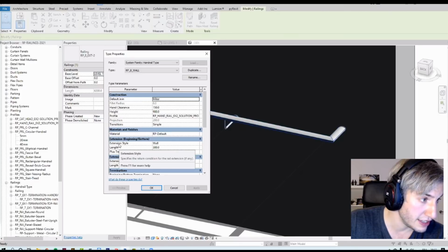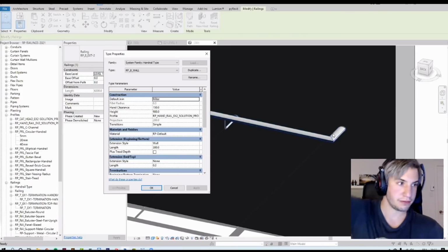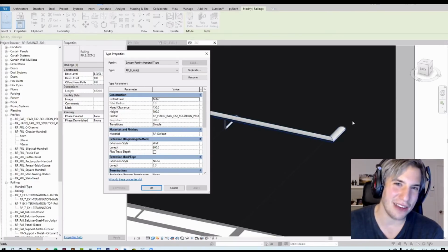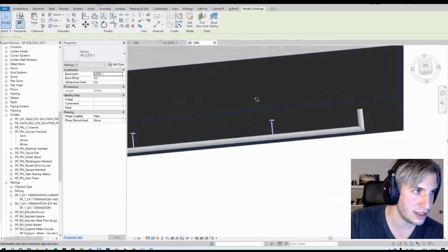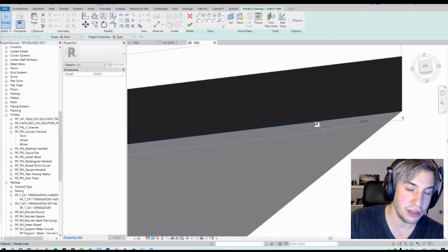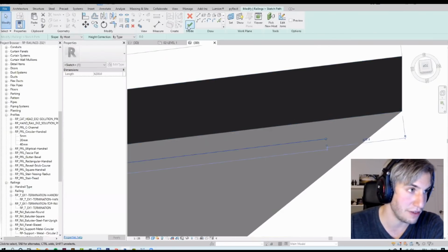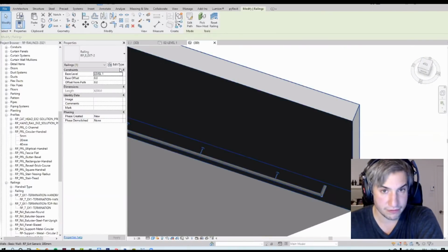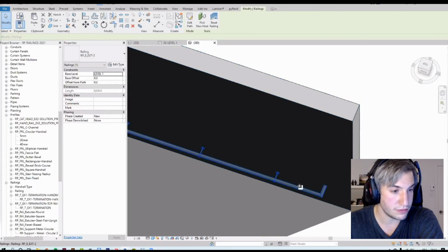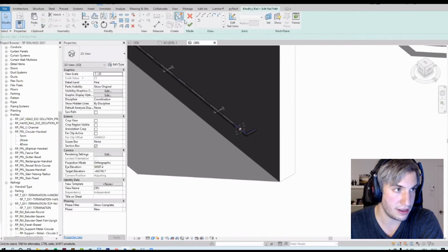With top rail, it is extension style wall. Basically, it flips around. And it doesn't really have to go to the wall. It actually goes to the purple boundary line of the railing. So if I was to move this, you can see it doesn't go to the wall. It just goes to the line itself. But then when you edit the sketch of that, just so everyone's following along, now you have the ability to edit that segment that's coming off. That's right. You could edit the path.